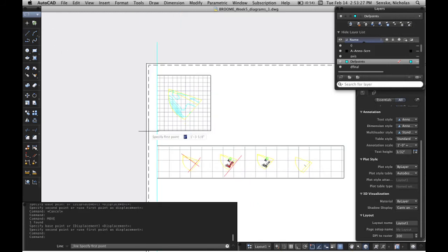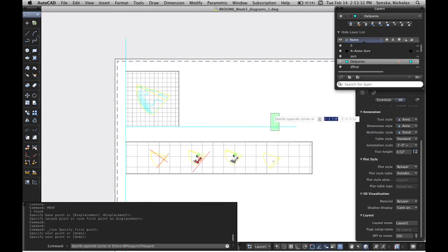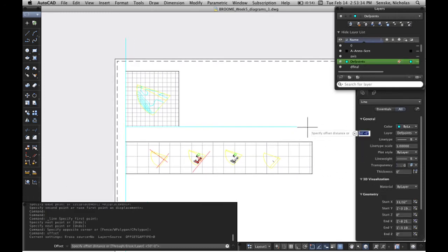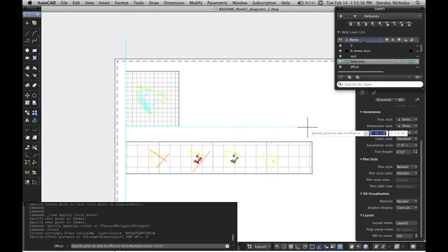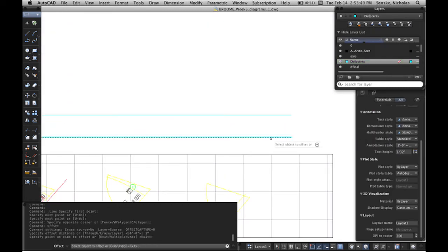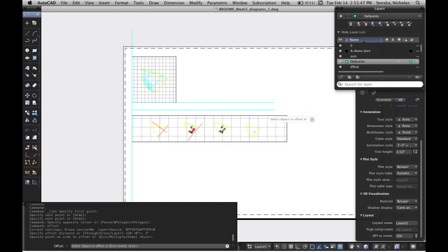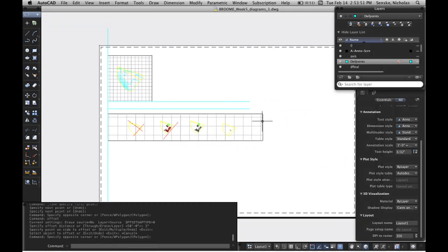So, you know, I could go in and now this might explain some things, Clark. So I'm in this space here. So I say offset 1 inch. So that's paper space 1 inch. Right. No, right? I get that now. Now this is an image of the model space. This is an image of your paper. So you can do things like say I want a 6-inch grid, and then you can just offset stuff 6 inches on def points.